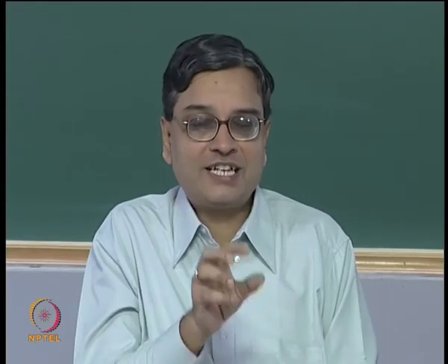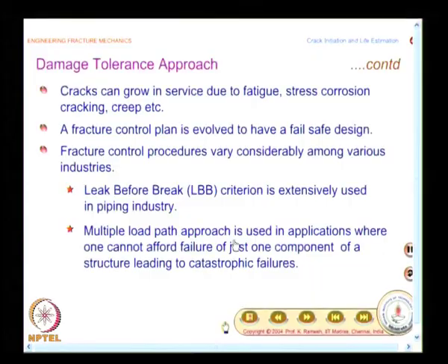Look at how nature has designed you, you are gifted with 2 kidneys. If one kidney fails, the other kidney will come to your rescue. So, there is optimization necessary, but essential redundancy is also required. See, you cannot design a structure such that if one member fails, the whole structure collapses. So, that is what this multiple load path approach is all about.